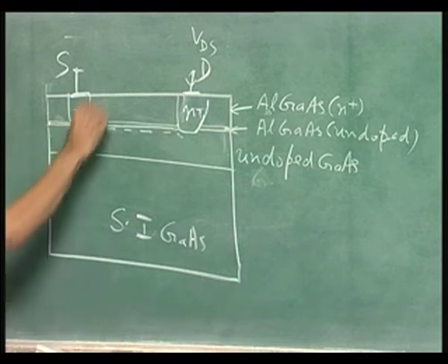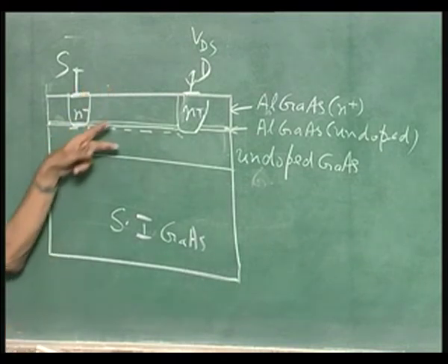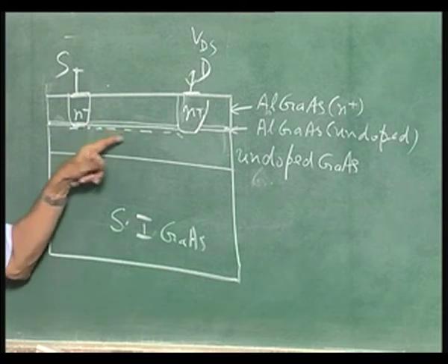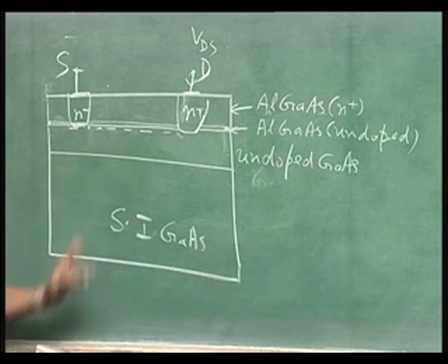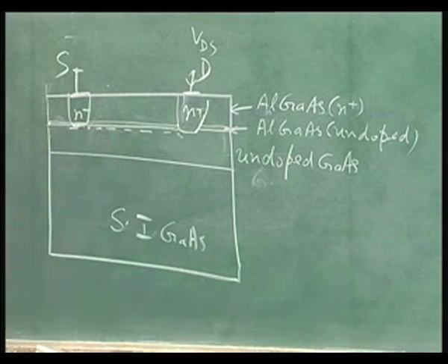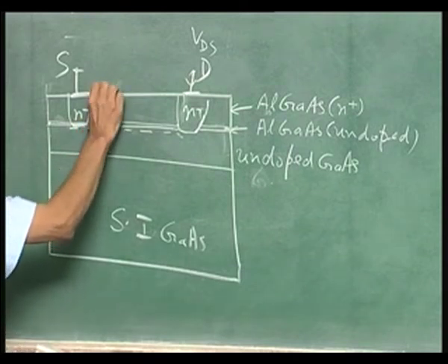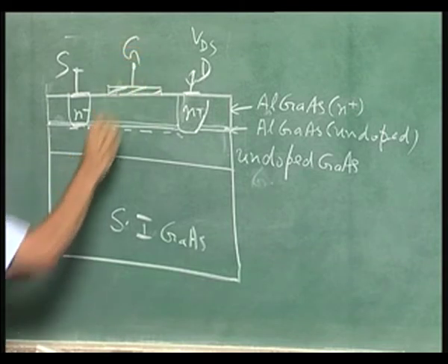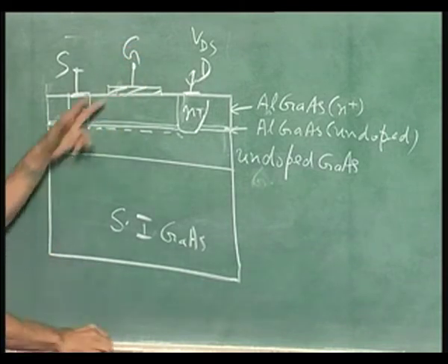To control that, how can you control this? How can I reduce this particular charge? I should either reduce or increase it. Okay. If I want to reduce that, I must reduce the band bending. Okay. So, how to do that? Of course, you must have another electrode which is put here, which is the gate. We will come back to this now.